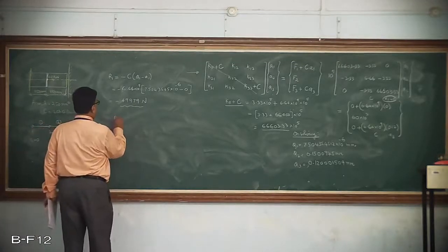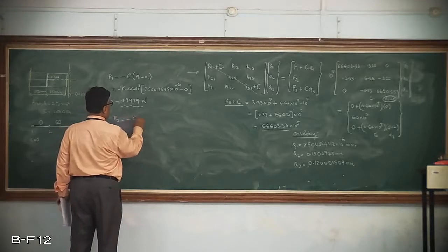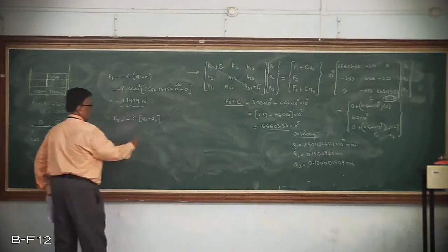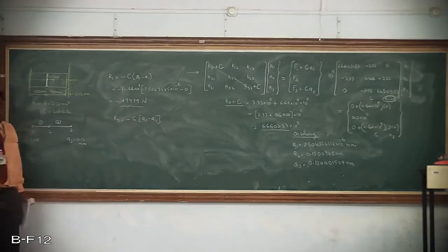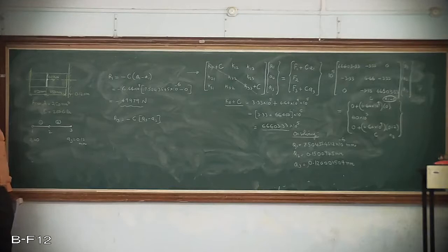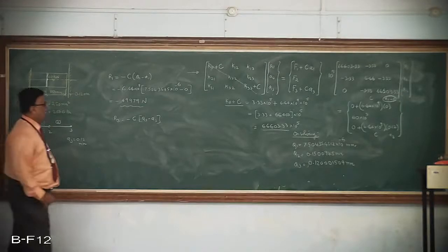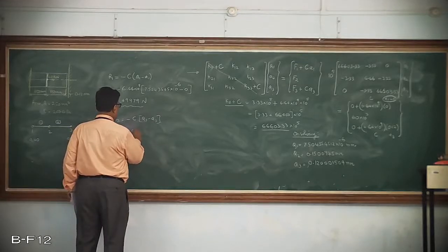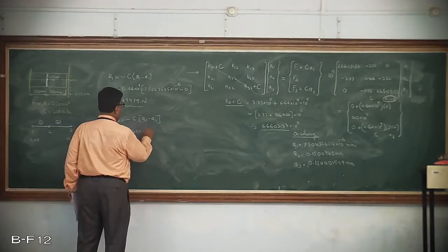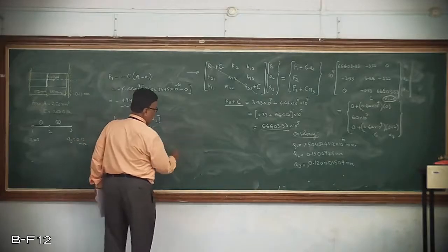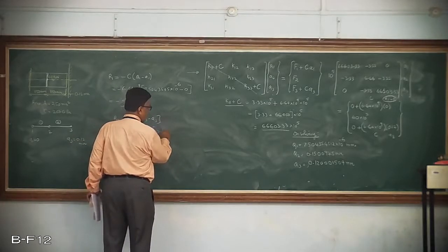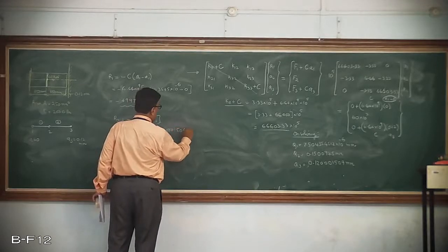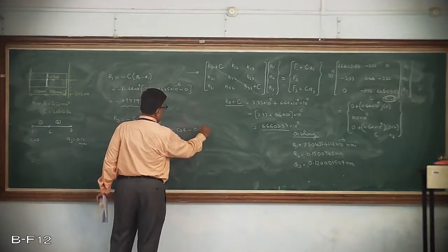In the similar way, you calculate the reaction here, which is going to be C into bracket Q3 minus A3 to get the reaction at the support 3 at node 3. We have to calculate this, which is nothing but minus 6.66 into 10 raised to 9. Q3 being point, look here, if by chance you did it by just directly neglecting all the terms here, then you will get the reaction as 0.